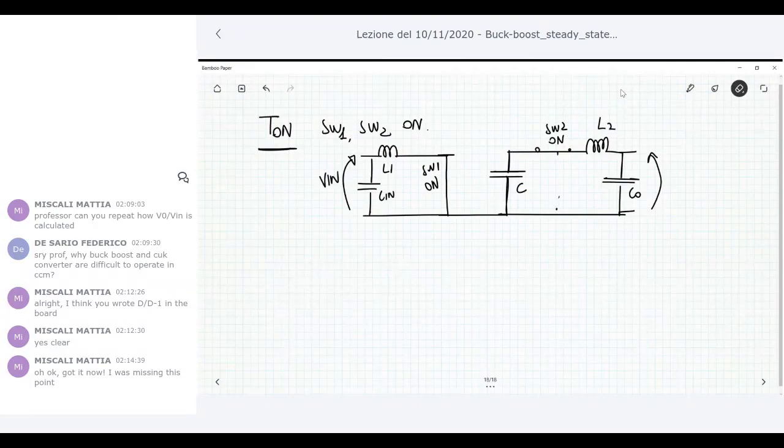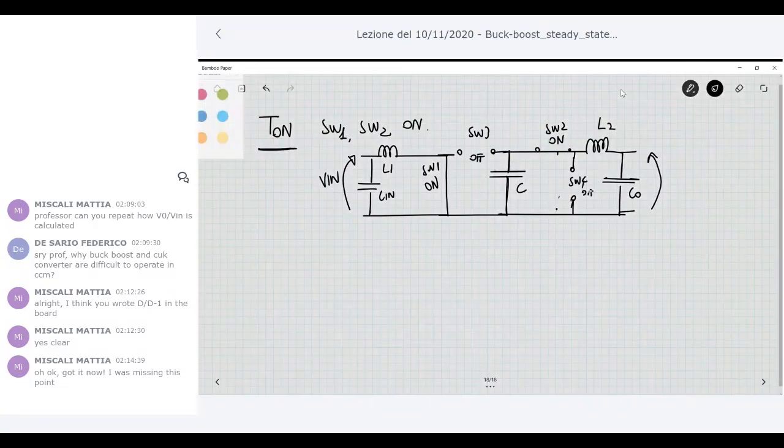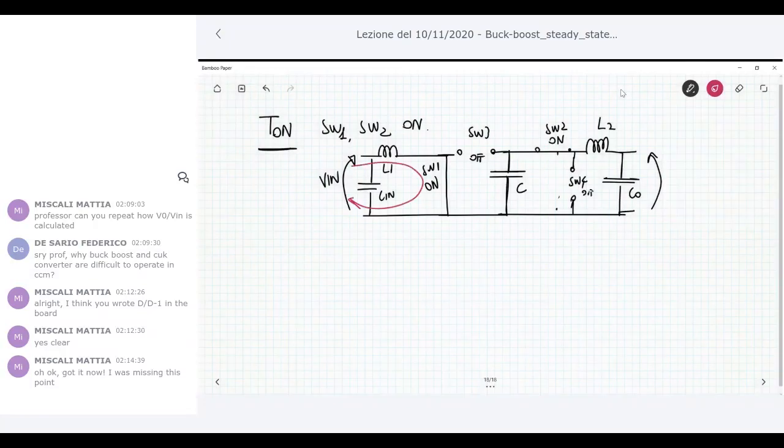These are the positions of the switches that are open here: switch 3 off and switch 4 off. So in that phase we can recognize the charging phase of the inductor, while the output voltage V naught is held to a constant value by the charge in this capacitor C naught and this capacitance. But there is no direct connection between the input and the output.